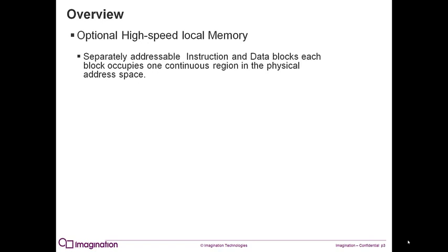The instruction and data Scratchpad RAM blocks are addressed separately from each other and from main memory. So it is possible for the Scratchpad addresses to overlap each other and main memory. There can only be one contiguous physical address range for each instruction or data Scratchpad block.